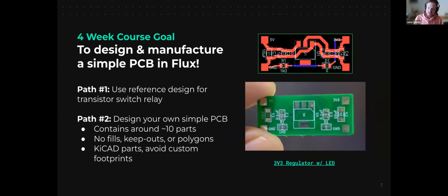The next one will be the relay. This is a single pole dual throw 5 volts relay. So let's add that one. SPDT SRD. Okay, there's one. As you can see here, this one is also a special part because it has a simulation model. As you can see, there's an icon for simulated, footprint, and 3D model. Let's add that one in here. And this one is again a very specific part because it already has a manufacturer part number tied to it.